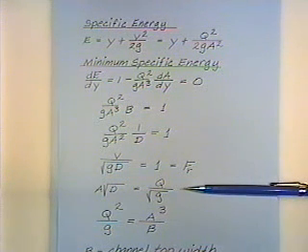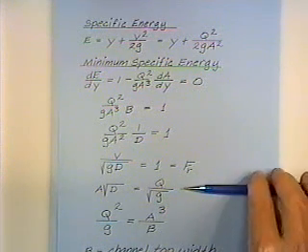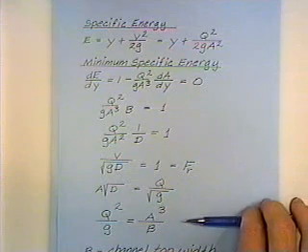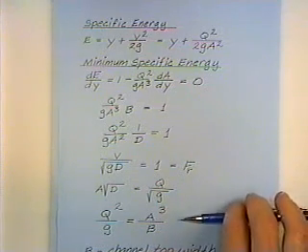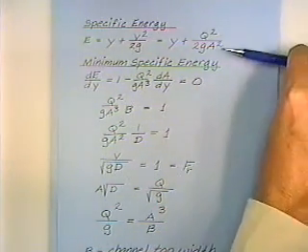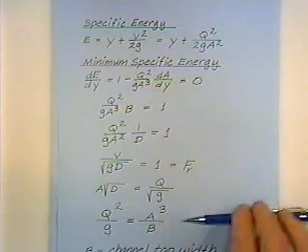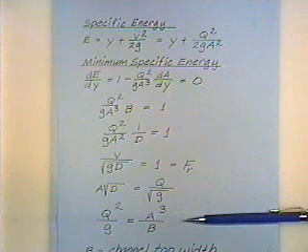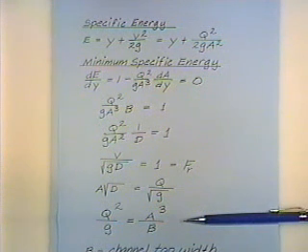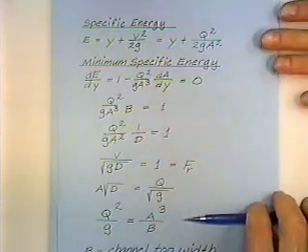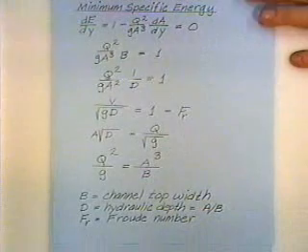And some of the textbooks and references will use the equation in that form. The Civil Engineering Reference Manual that you have, as I recall, uses this form, which is common in many references. And so all these steps are just mathematical manipulations, and this is an equation that's useful for solving problems. Q squared over the acceleration of gravity is equal to the area cubed divided by the top width. And the different terms are defined at the bottom there.